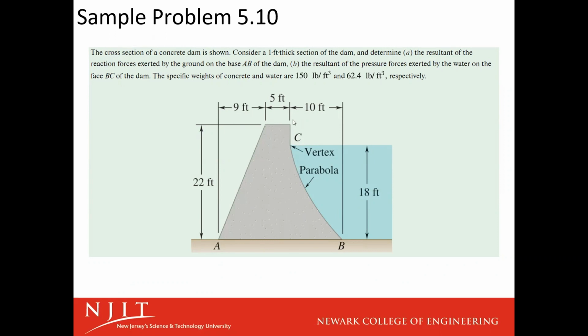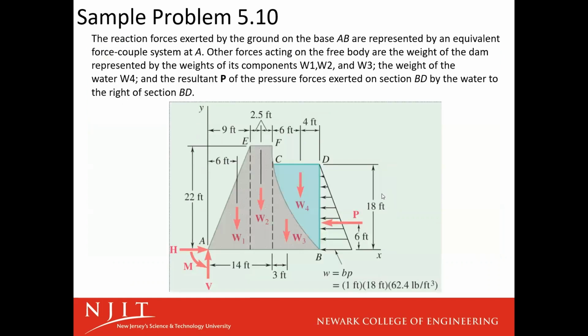So slice this into profiles. We recognize a triangle, a rectangle, a parabola. Then we have the inverse parabola of the water. We can find the weight of each of those areas. And then we'll have a distributed load over on this side for our water. So there's a distributed load in each of these weight elements. Yes, there's also a distributed load in the water hitting the dam, hitting the concrete. Remember that your depth and pressure have a relationship with each other.